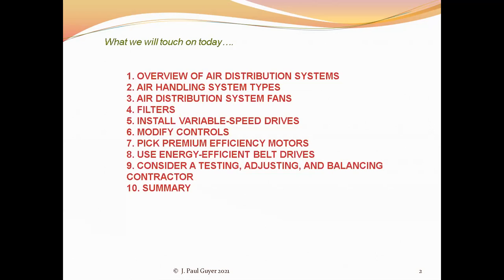The refrigerant typically goes by pump pressure into the coil in the evaporator heat exchanger, and then the building fan blows the air through the evaporator, and cool air is pushed into the duct system, and it goes to the occupied spaces, and then it is sucked back by the return duct system or by a plenum return system, and it just keeps getting recycled and recooled, or on the heating cycle in the winter it's heated.